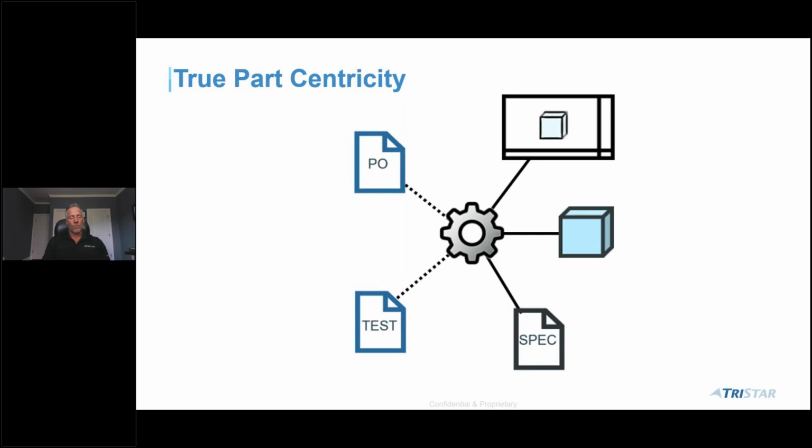There are a lot of considerations when they do. If all three are matching revision, you may be revising models and drawings where you do not actually change any of the fit or the form of the part. In that example where I need to change out maybe the material spec, I would be revising a model and a drawing with no dimensional changes, and that can become cumbersome depending on the organization.